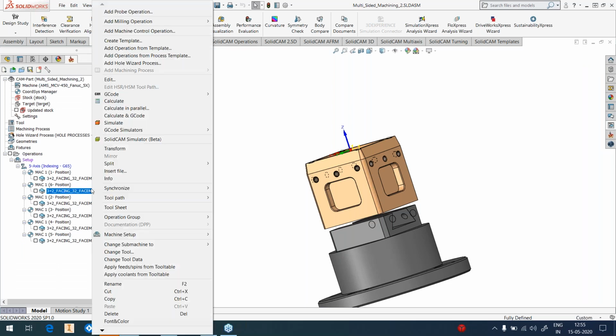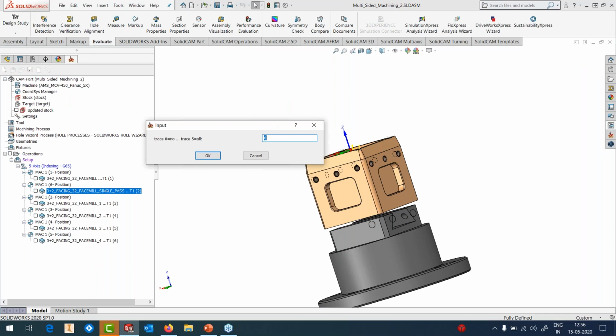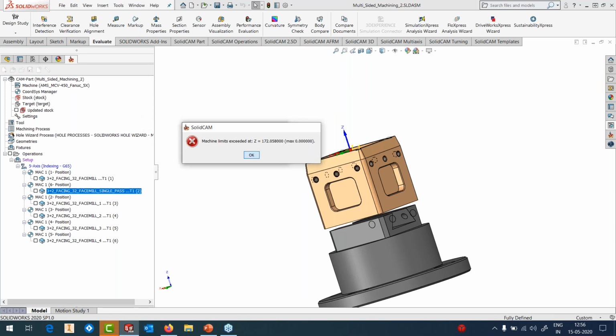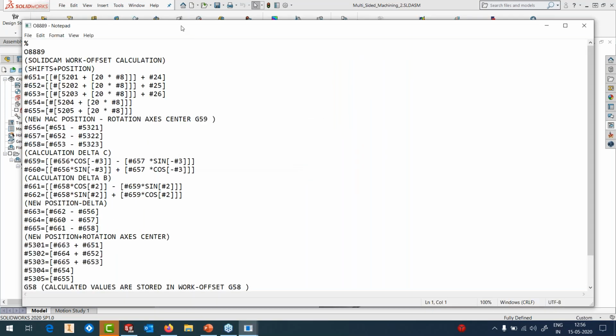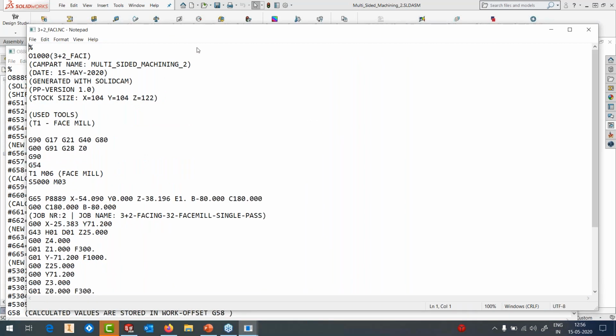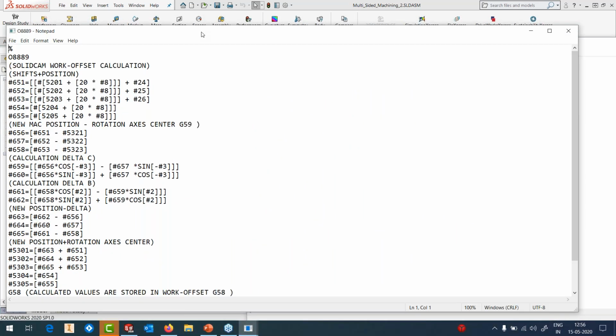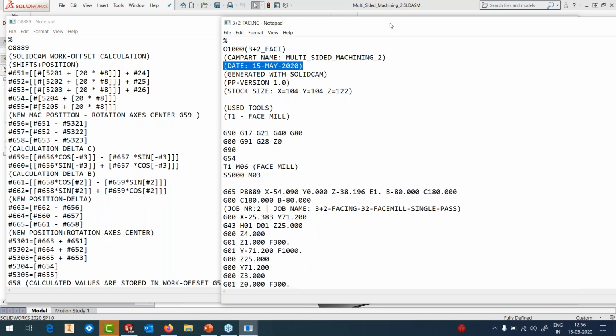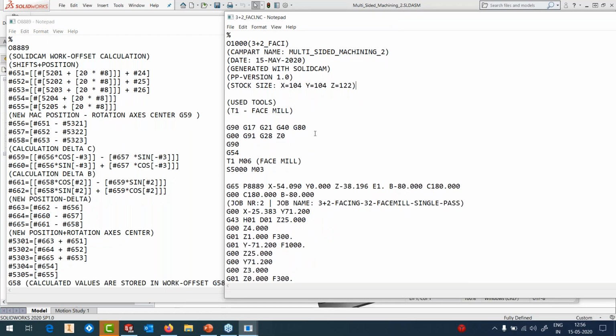And the same single pass program, I'll generate the G-code now with a Fanuc output. Okay, so you see that you're getting two programs here. Let me explain these programs to you because they're pretty interesting. First of all, this is my main program, wherein it calls, using the G65 function, P889. The P889 basically is the same 889 macro call calculation, or a macro calculation.